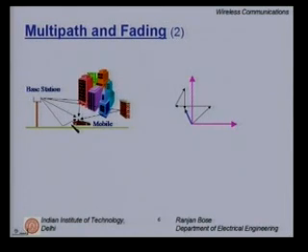However, since the mobile is moving, when it moves a little forward, the multipath changes, and in the next instant, because of the reflections which are different now, you get a different vector sum. And look, this time the signal has really gone down. Not only the amplitude has changed, the phase has changed also.